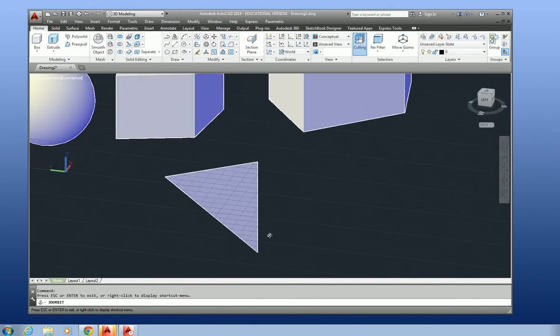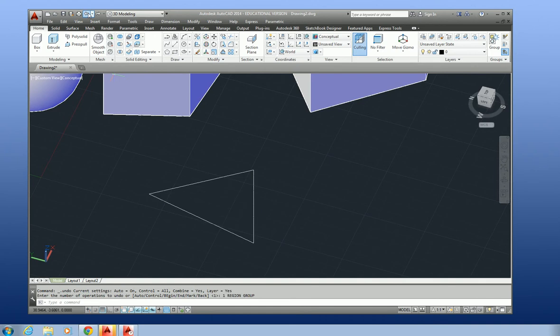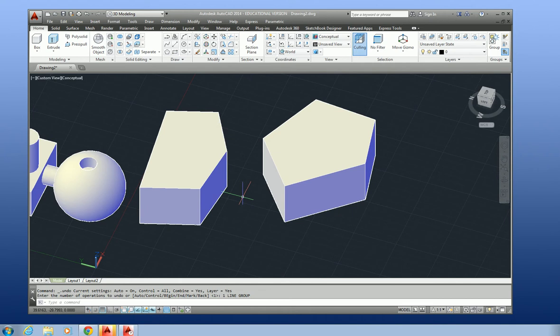And I'll tell you why this did this. It's because when I was working with my line, I really wasn't connecting it to anything. And then sometimes region doesn't quite work the way you want it to. So with that said, there is more than one way to connect a line and then extrude. Keep that in mind when you're making your shapes, because one way may be a little more difficult to work with. And I've found that to be the region tool, believe it or not.